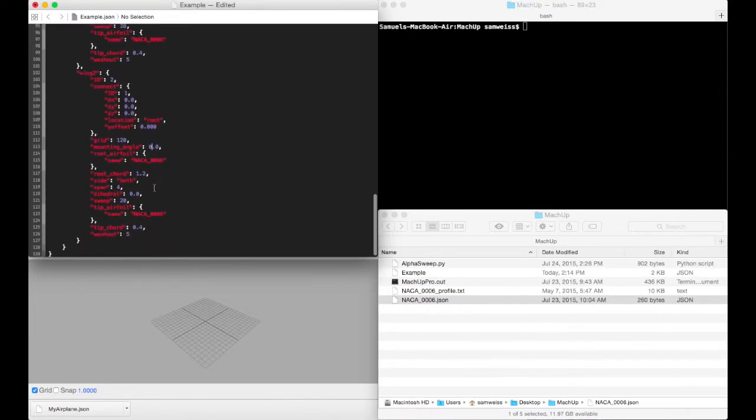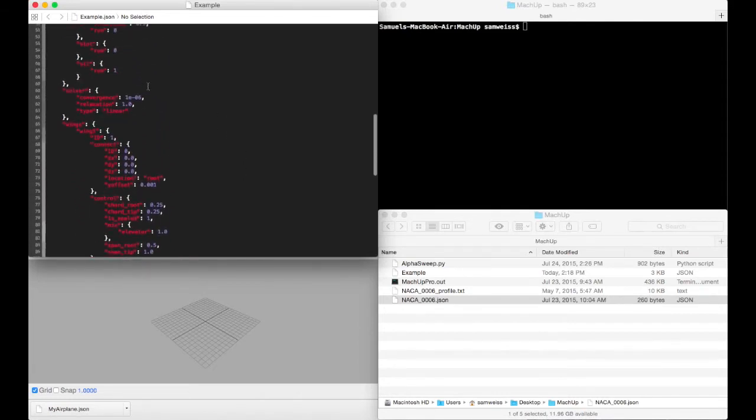We'll use the same airfoil for simplicity right now. The root chord, we'll make wingtips. So the root chord is going to be 0.4. It's going to be on both sides, a span of maybe 1, dihedral of 80 degrees, sweep of 20 degrees, NACA 0006. And we'll just put in 0 washout. So we've just added a wing here, wing 2, and they're going to be wing tips.